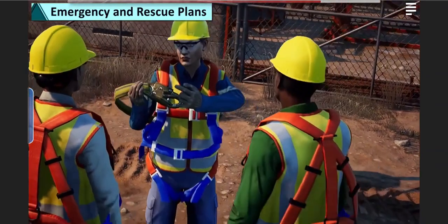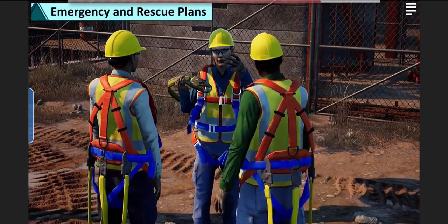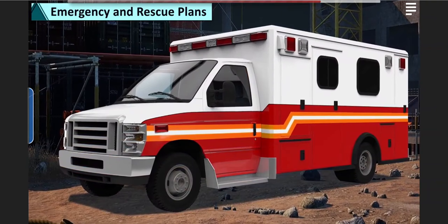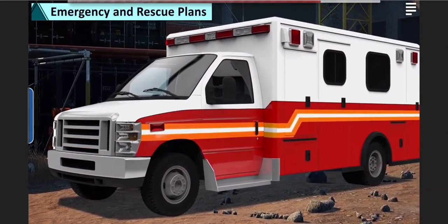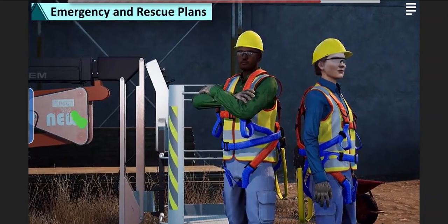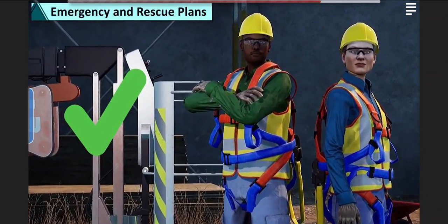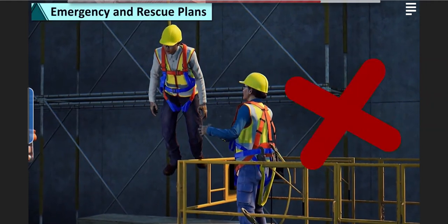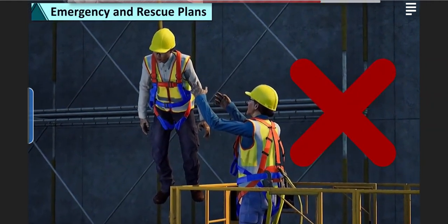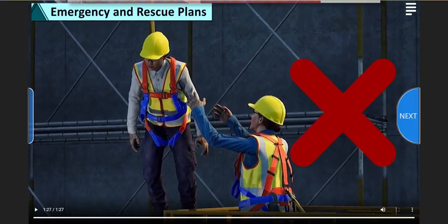All occupants who will use a fall arrest system must be trained on procedures to follow if they fall or see someone else fall. If suspension trauma or other injury or illness is suspected, the affected worker must receive immediate professional medical treatment. Rescues should only be carried out by properly trained and authorized personnel, following company procedures. Never use another MEWP or other piece of equipment to assist in a rescue, unless proper procedures for doing so safely are included in the rescue plan.